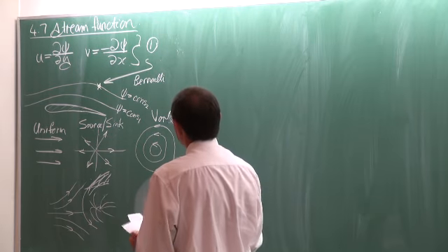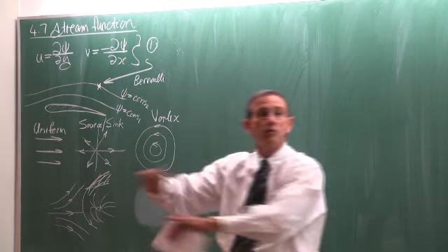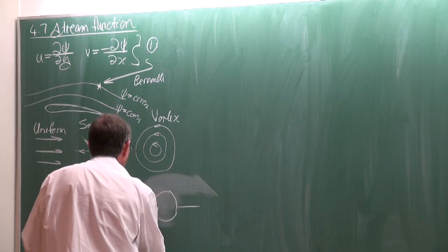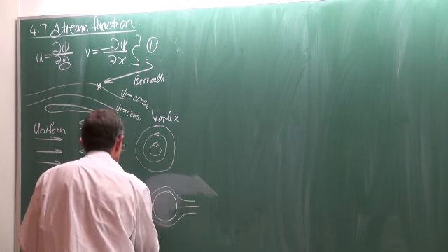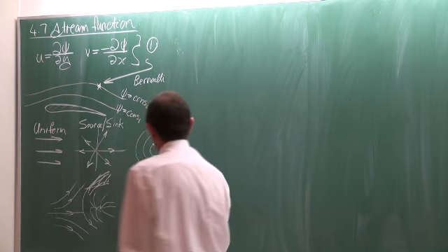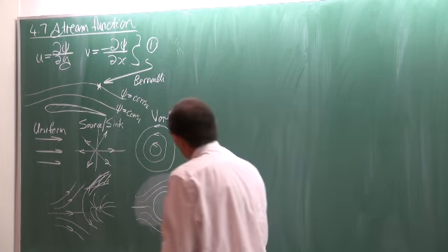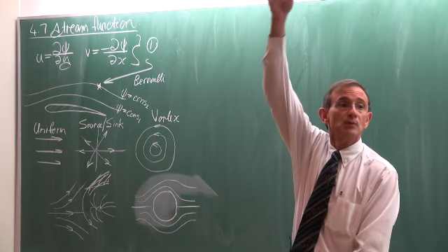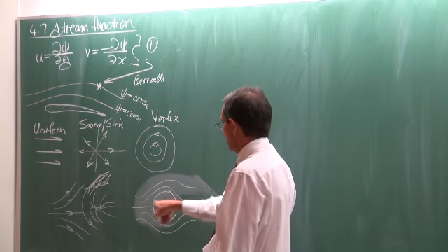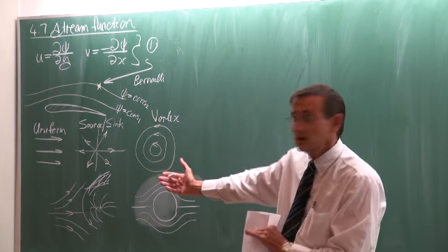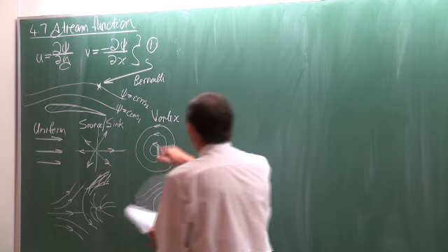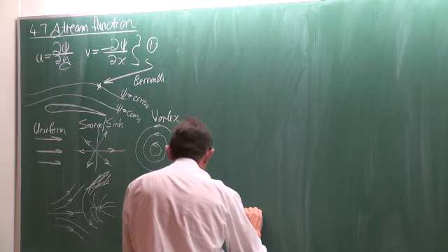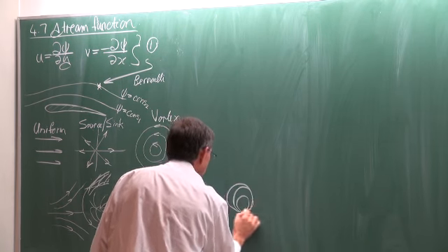Now, what they also did is they started putting sources and vortexes and uniform flow fields together, and the result was that it was possible to get the flow field around a cylinder. Again, there are not many practical applications for flow around a cylinder, but there are big chimneys, typically along a chimney like that. Now you can get all the velocities and the pressures, and then also start rotating stuff. And the result of that is that you can get flow fields typically looking like this.